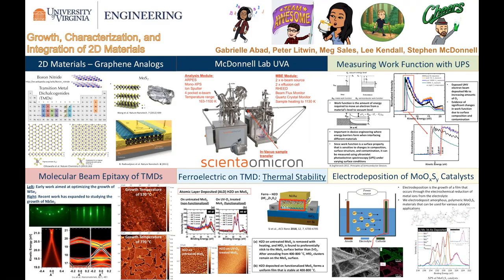Now, the top right there, you're seeing some work that's recently been done by Gabby. She's interested in niobium silicon Schottky diodes, and the Schottky barrier is related to the work function of the niobium. And what she's been looking at is how that niobium work function depends on oxygen exposure. And so the spectra there on the right-hand side are showing you just how sensitive it is. She can vary the work function by over 1 eV by exposing it to different concentrations of oxygen.